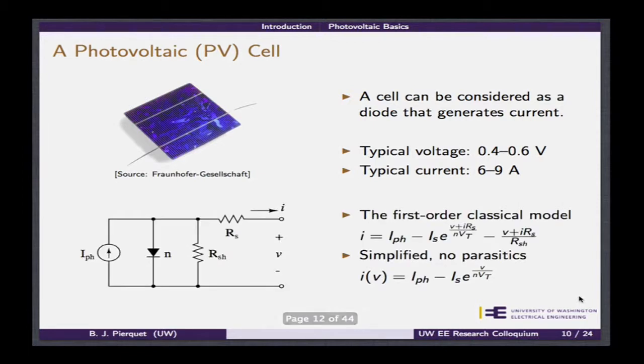And so we'll talk about that in a second, but if you want to model this in a circuit, what you end up looking at is a somewhat complicated model, at least a first-order model, that sort of captures the photovoltaic current, essentially the current due to the incident light. You have a diode. It's essentially a PN junction style, and so you have the diode behavior. And then you have parasitics.